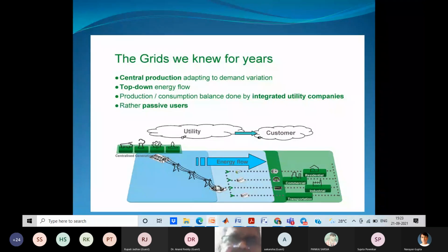If there were no load, there would be no electrical engineering. Load modeling is a very important topic. Please study that properly. There are three types of load model: impedance model, current model, and megawatt model. Current model is mostly used in protection. Impedance is used in faults and fault diagnosis, and megawatt is used for load flow, economic operation, and stability. So these three things you should know.